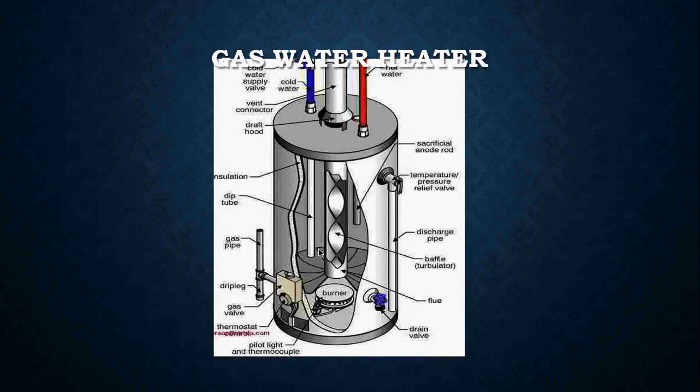What's nice about gas water heaters is that we are actually using the flue pipe to heat up our water, not only the burner but also the flue pipe. The jacket, which is right here, is our insulation, and it is what keeps that water heater all nice and warm. So the thicker the R value on our insulation and on that jacket, the more efficient your water heater is.